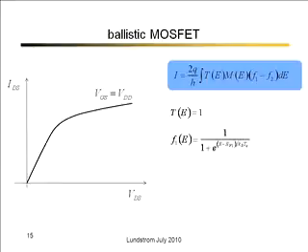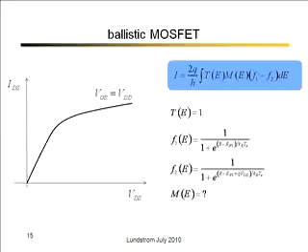We have a Fermi function in the source. We have a Fermi function in the drain that has a different Fermi level; the Fermi level is lower by Q times the drain voltage. And we have to figure out what the number of conducting channels is. And then you have to add in MOS electrostatics. One of the things that makes a MOSFET special is that the Poisson equation is so important, this MOS electrostatics. So that has to be part of the picture too.